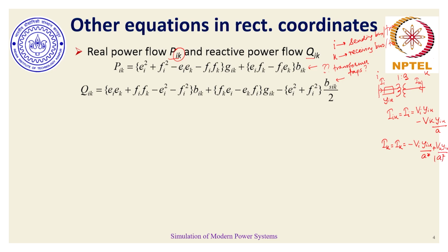So, for transmission lines, which are similar to transformer taps with tap equal to 1, the previous current expressions that I wrote would simply boil down to the same expressions, the difference being that half line charging susceptances would not be present. But even if, theoretically, we have a transformer tap along with a nominal pi model of the line superimposed, then these expressions would also have the corresponding half line charging susceptances present, as we have seen earlier, which I am not going to write in detail.